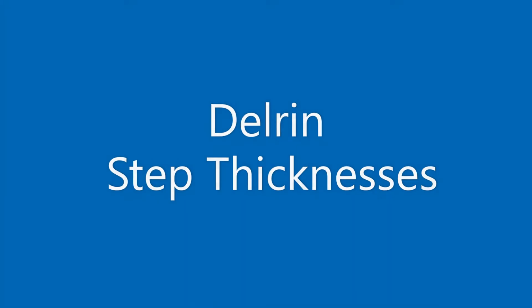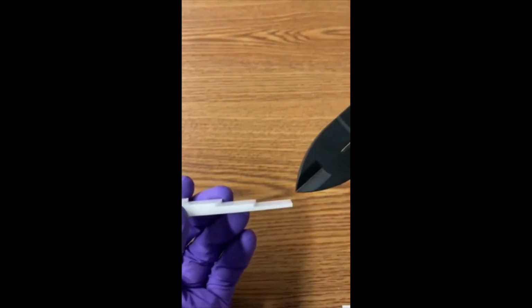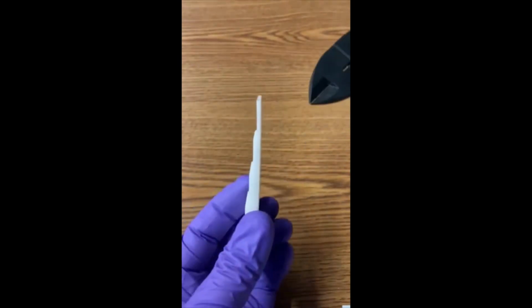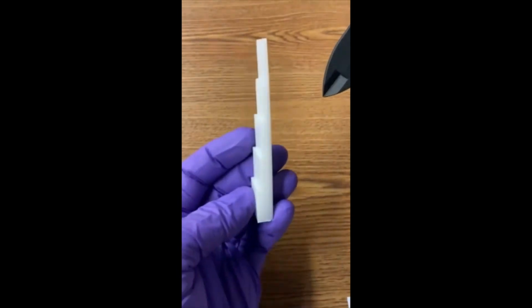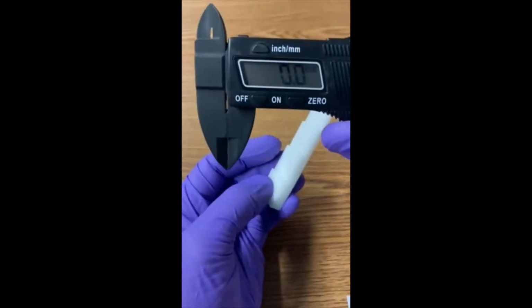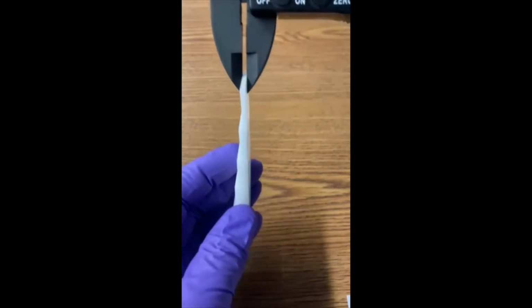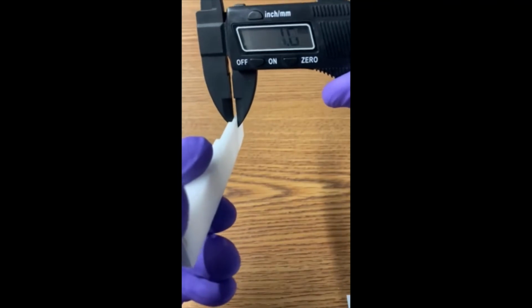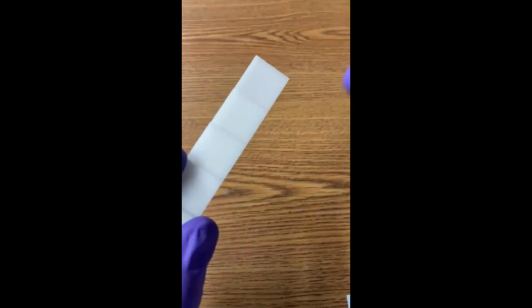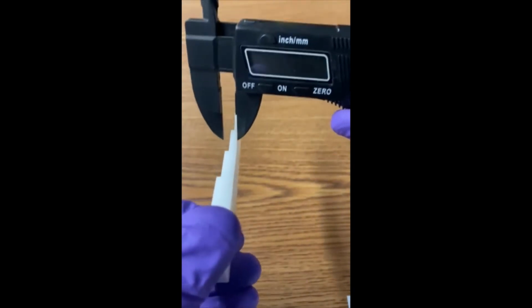We now take the Delrin step sample as an example of the measurement for the step sample thicknesses. We measure the thickness of each of the 5 steps. We're going to do this so that we know the distance the ultrasonic wave is going to travel, going from the front surface of the step to the back, and then back to the front where the transducer will pick up that signal again.